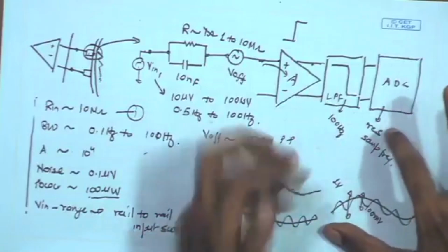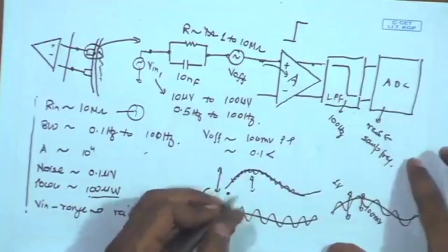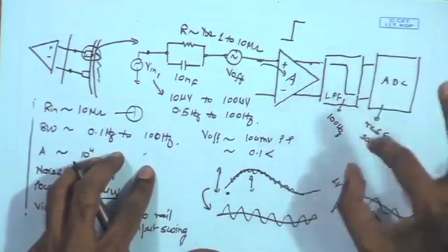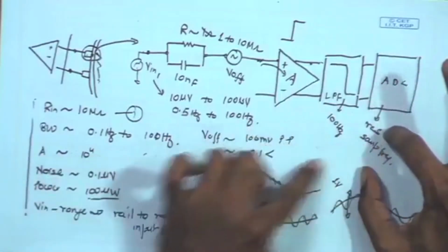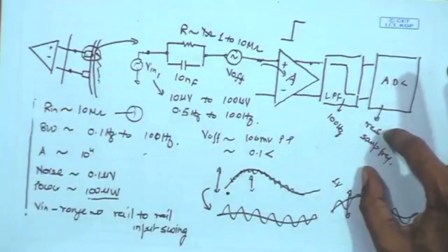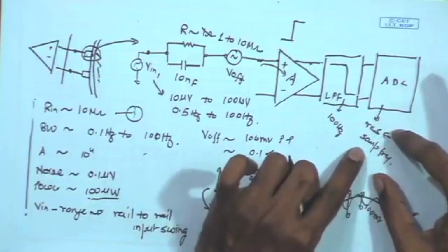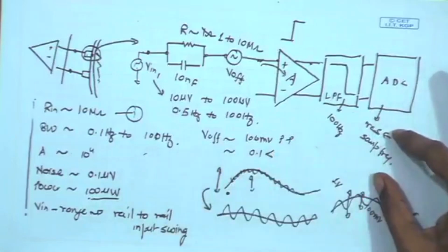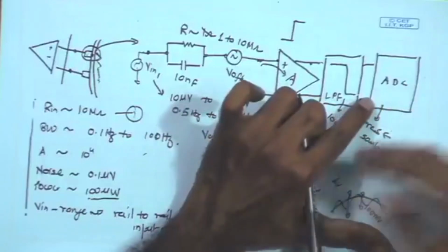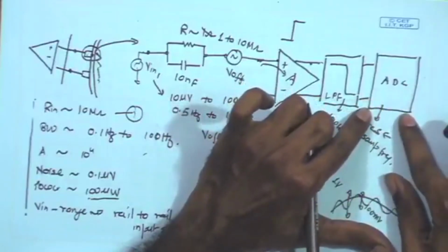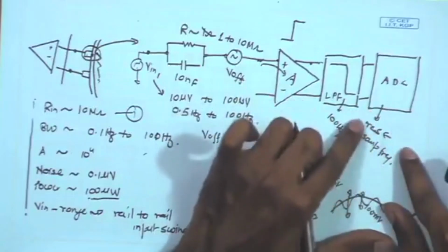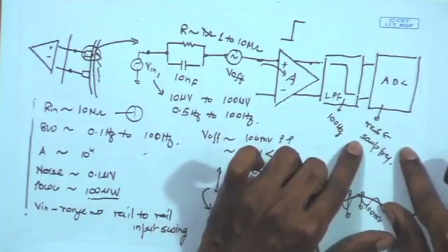Bit precision comes from the end user, as we have discussed. The people doing the signal processing on the digital side may tell you that this much bit precision is required, and that has in fact translated to one of our input specifications, that is the input referred noise. Likewise, there can be other specifications related to linearity that we also need to consider over here. Linearity and distortion play an important role in determining the specifications of the ADC, and we will visit those also. But two very fundamental specifications are resolution and sampling frequency.